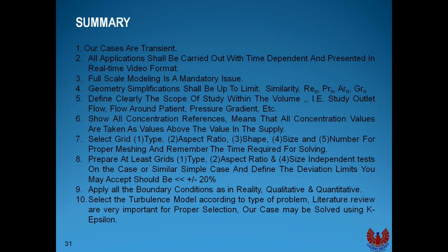So you have doors that shall be open and closed. This means that we have to control the pressure also. So we have to control the temperature, the local velocity, the pressure, the humidity, and the air contamination inside this room.